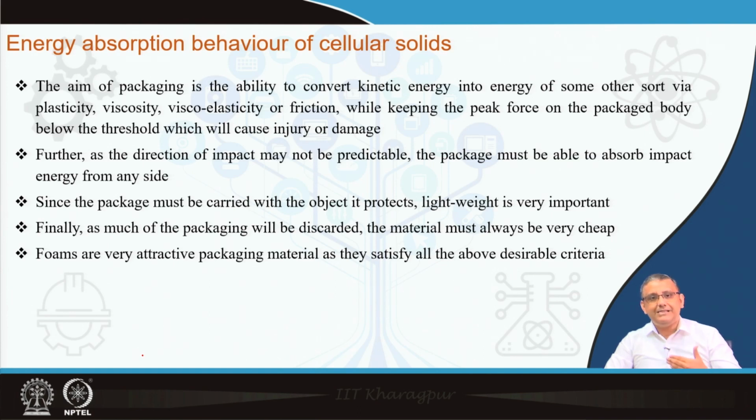The main aim is that the foam material will undergo deformation. That means whenever there is a very high velocity crash, the foams will undergo deformation, and by doing so they will absorb the crash energy and protect the occupants of the car from the actual crash energy.